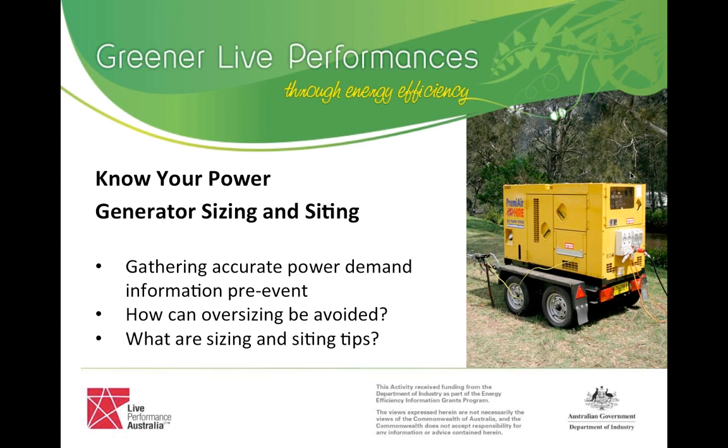We offer a service where we can advise you on the lowest amount of cable to be used. You obviously put your biggest generator where your biggest load is, and try and distribute from there, limiting the cable run so you don't have volt drop, and peripheral generators for catering and those types of things, we can help size for those.